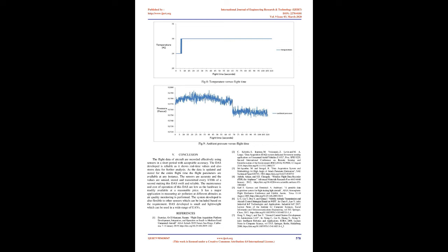For example, in the above-mentioned string to extract pitch angle, the match string function is specified to identify X character and the subset function extracts the adjacent numerical string 000. Later a conversion function is used to convert the numerical string to actual numerical values. These numerical values are displayed on the GUI using plot function and also stored in an array for further references.